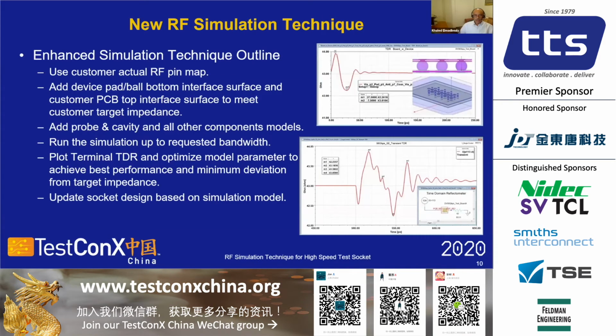Okay. So here, usually we ask the customer what is the rise time for their test measurement or test setup. We are putting 25 picosecond as a rise time, and this is a good starting point. We have some designs we did at 15 and some at 35. So 25 picosecond rise time for the time domain reflection. This is our setup.